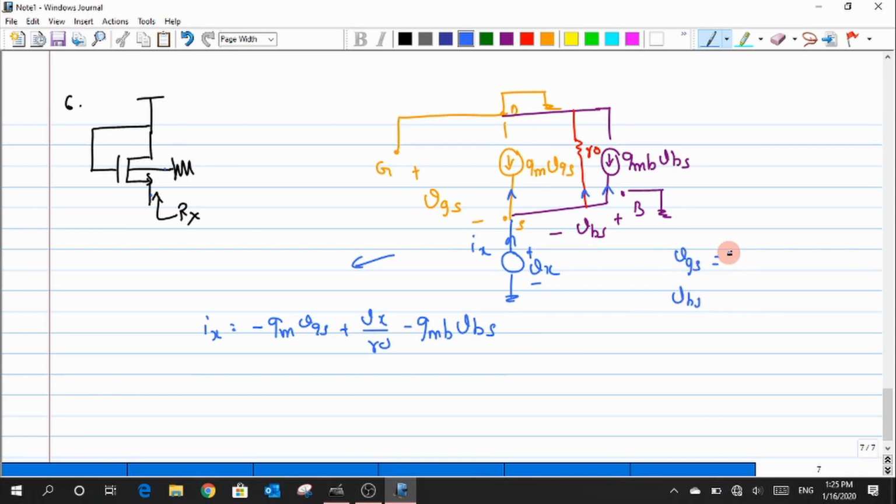So I just apply the same principle of following this Vg minus Vs and see what is there inside each of them. In this case, the gate is connected to which terminal? To which potential? It is the drain, and the drain is again connected to ground.